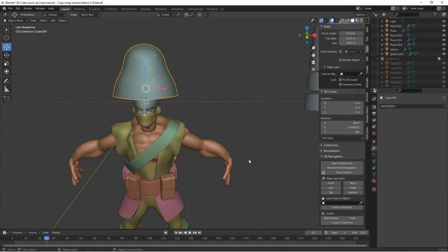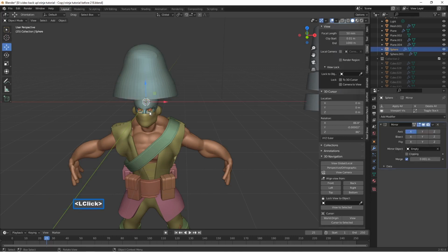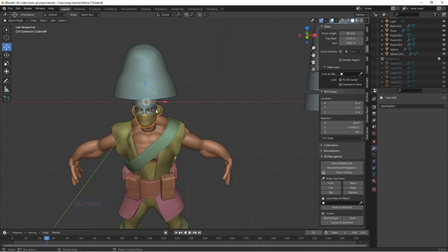So just so you can remember in the future, we put on a cube, we put on 2 subdivision surfaces to get our basic shape, and then we shaped our Ninja hood, and then we put an additional 2 subdivision surface modifiers on and then applied them, right? So now with those applied, we're going to select our face.